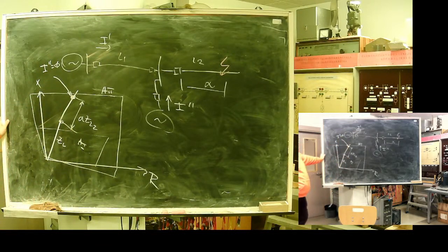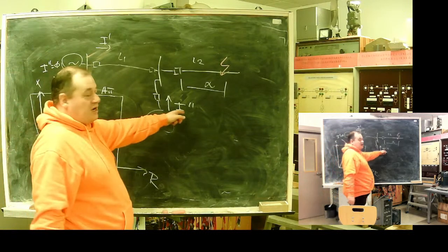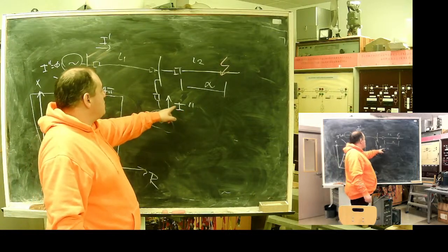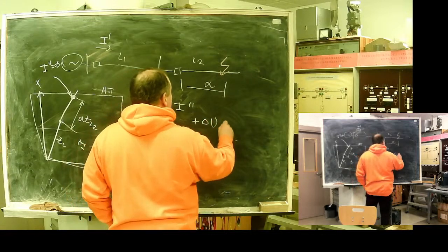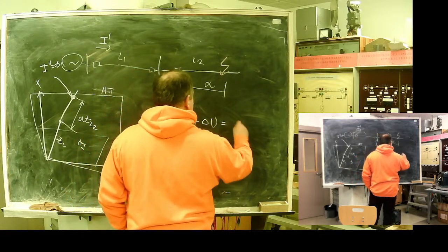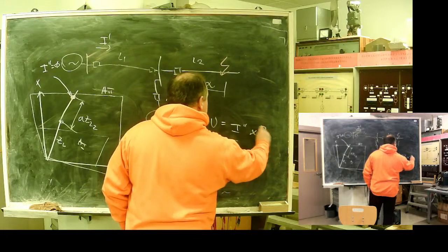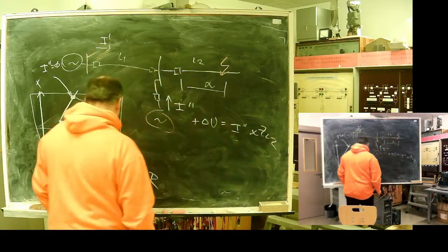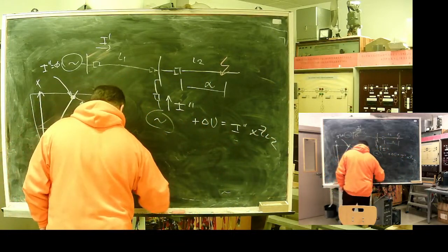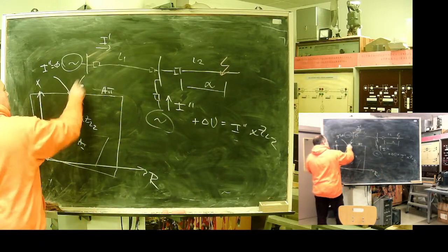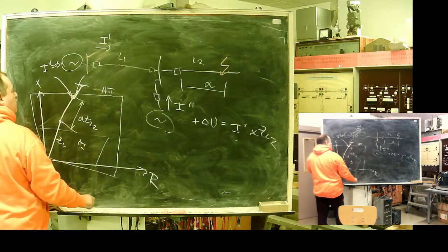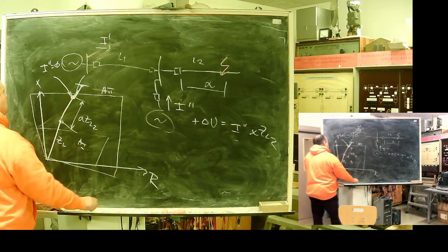What happens when we take this current into observation? It causes an additional voltage drop equal to I2 alpha ZL2, and it shifts the observable fault forward.